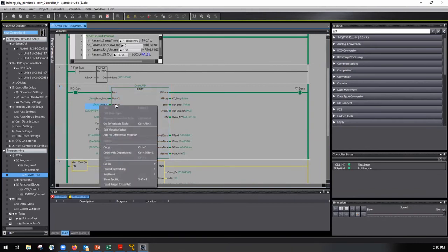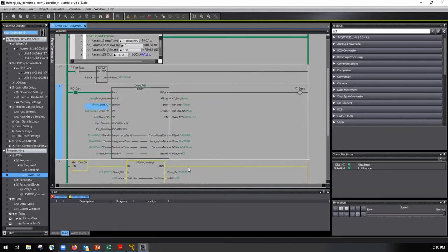And you don't have to flip the start auto tune bit false, but I like to. It's not going to re-auto tune until you flip it true again, so it auto tunes on a rising edge. You guys are welcome to change your set points around now, see how it reacts. Is anybody having any difficulties? Does everybody's PID loop appear to have tuned properly?